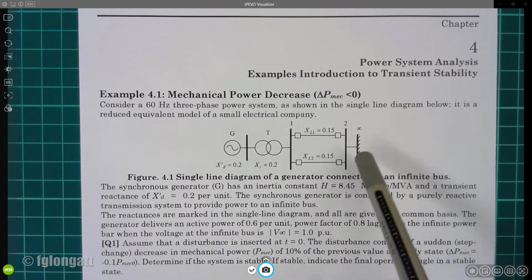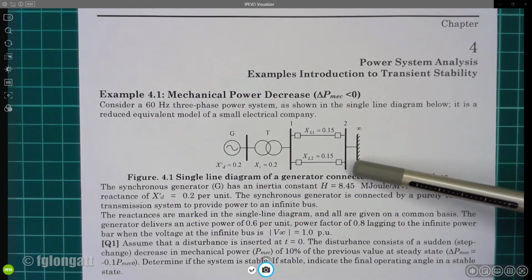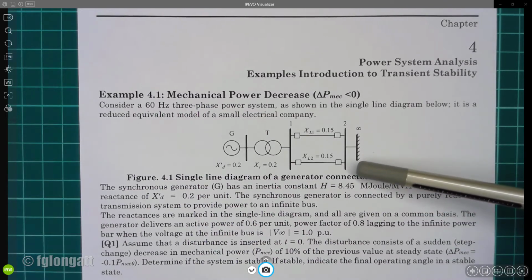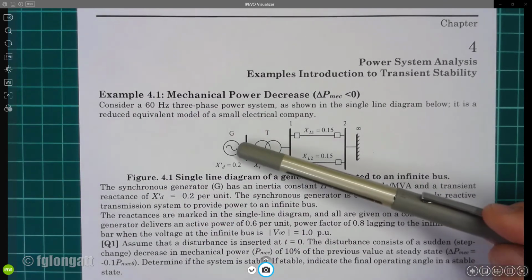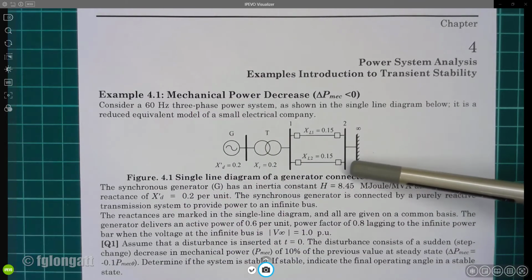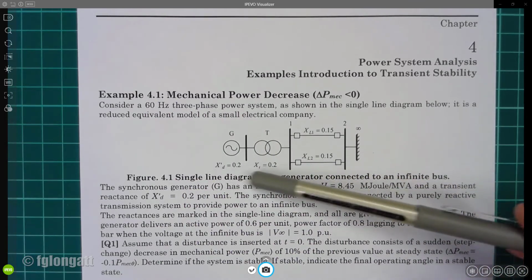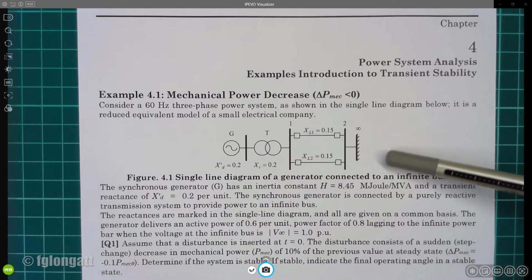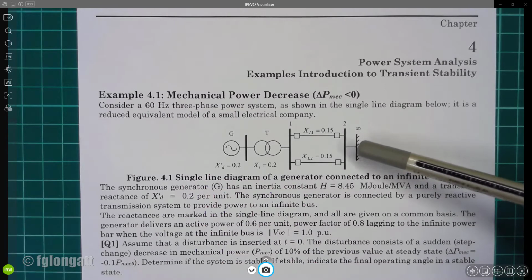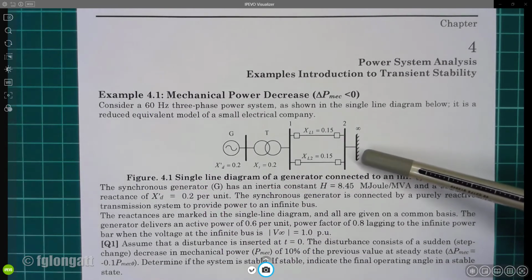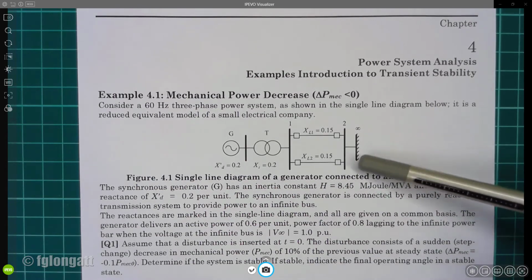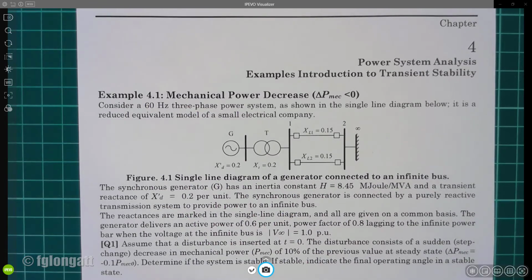But the reactive power is a bit different. This problem is giving you the power factor here, 0.8 lagging, because the reactive power here is different from the reactive power there. You have many losses across the transmission line and the transformer. That means the reactive power that you send here is not the same reactive power that arrives there. Take that into account. The power factor is given there, the active power is given there, and also this beautiful infinite bus bar is working at 1 per unit.